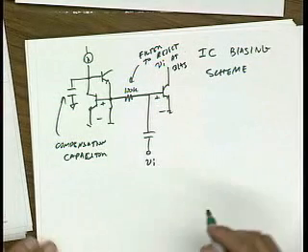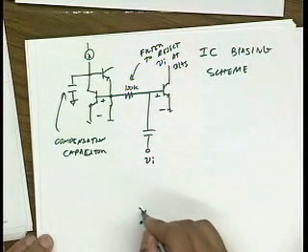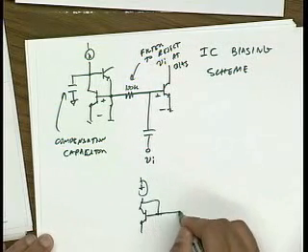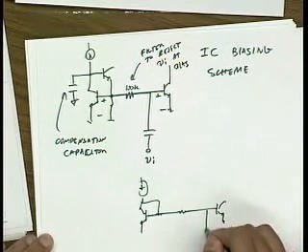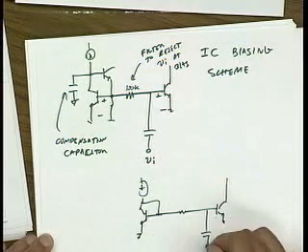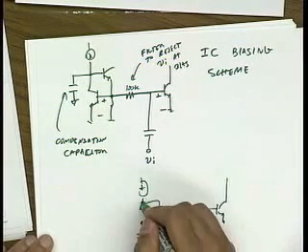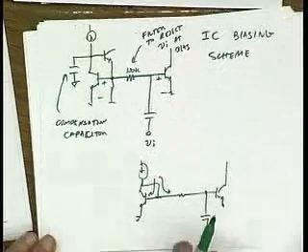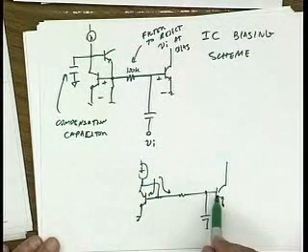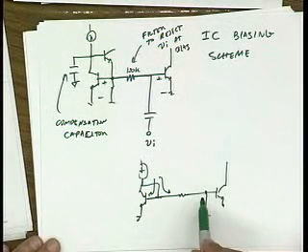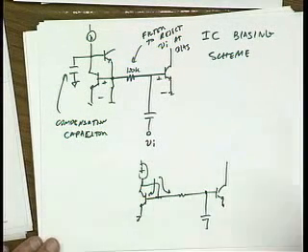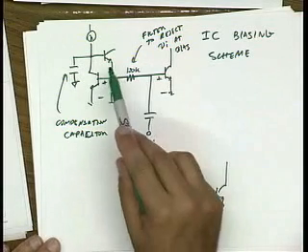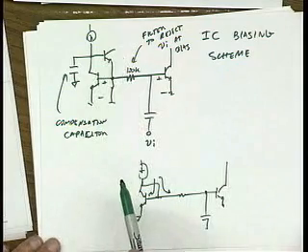Okay. I could have also just used a simple mirror. And the circuit would also work fine. The difference now is that, first of all, I have base current. And if base current flows through this resistor, it varies the VBE of this device, right? So that's kind of bad. I'd like to get rid of that because base current varies over temperature a lot due to beta variations. So here, this is basically a helper transistor to lower the base current.